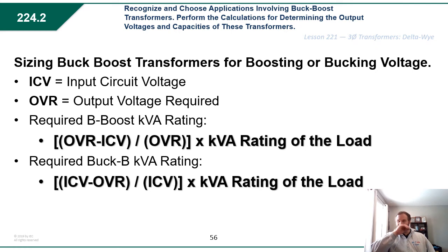Sizing of buck boost transformers for boosting or bucking voltage. Your ICV, that means your input circuit voltage. Your OVR, that means your output voltage required. These formulas here will be used for the calculation of sizing buck boost transformers for either bucking or boosting. Note that the first one here is for when you're sizing it to boost, and the second one is when you're sizing it to buck.